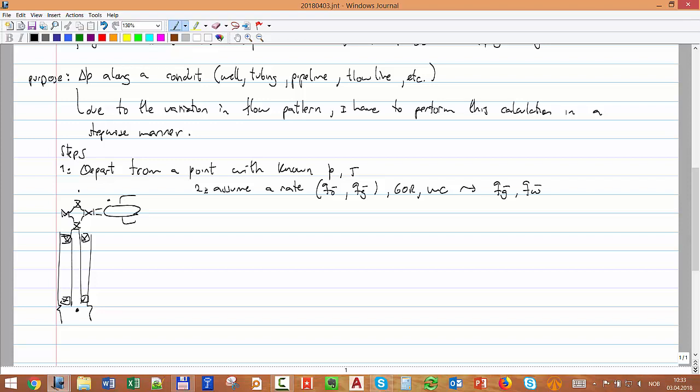After I have that, remember, for gas or for liquid, what causes the pressure drop is not the standard condition rate, but the local condition rate. That's what causes the friction in the pipe. So it's exactly the same thing, and I have to calculate those rates. I have to calculate the local rates, and I also have to calculate the fluid properties.